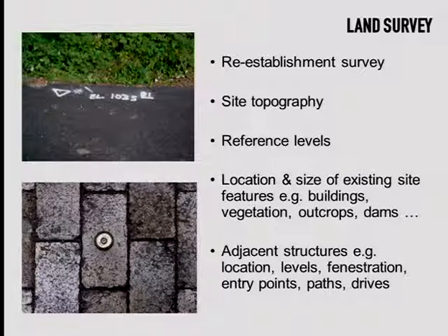And if there's any existing structures, well, we need to plot those really accurately as to exactly where they are, because we might incorporate those into our design, okay? Or we might knock them down. If there's trees, well, we might retain them. We might design our building around them. And we need to know the relationship of the adjacent structures to our site.